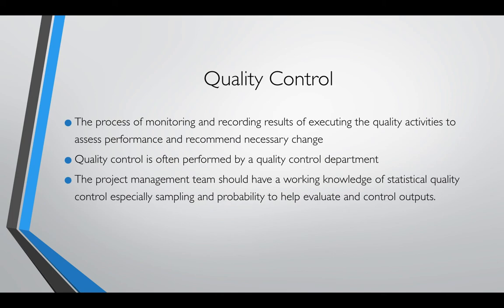On a design-bid-build project, the contractor performs its own quality control measures. So they hire all the testing, they do all the recording of the information, all the measurements, and then the state, the agency, the client, whomever, is going to have their own quality assurance team. Depending on the contract, this is going to change who holds the responsibility for quality control. But for the most part, quality control is done by the contractor.